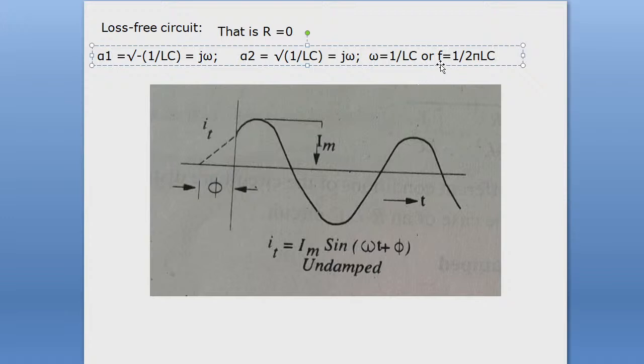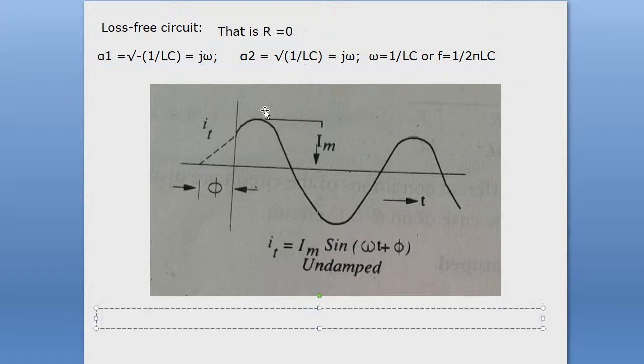So this is the oscillation frequency of this circuit. Therefore, this response is known as the undamped response for this circuit. If you put the values of this factor, you will ultimately get the expression for VC. Here I have put i of t. In terms of i of t, you can write i of t equal to C dVC(t)/dt. You just multiply and simplify, and you will get such a response.